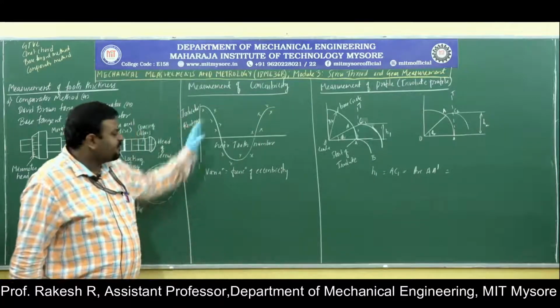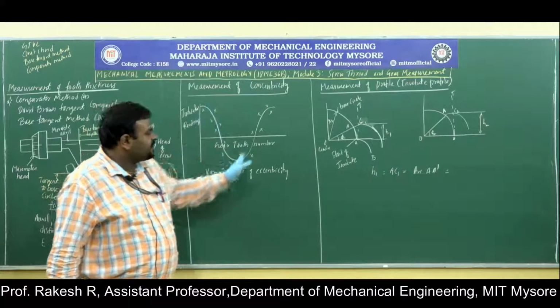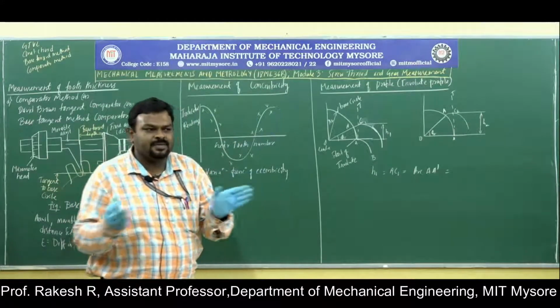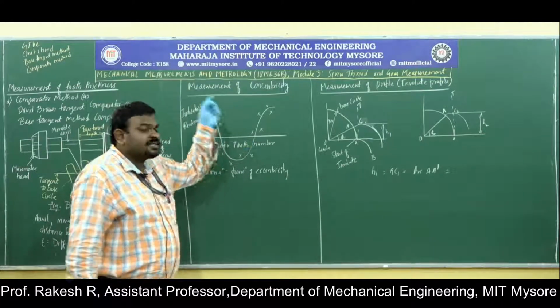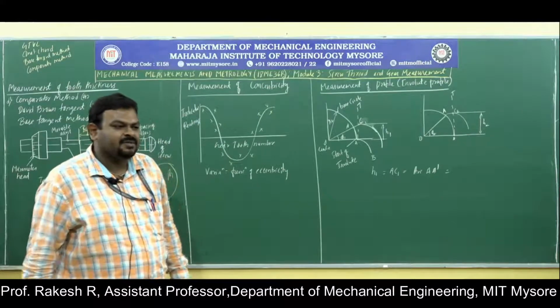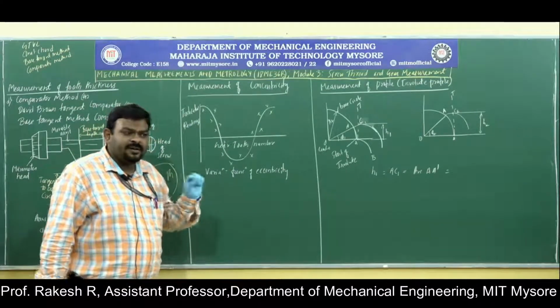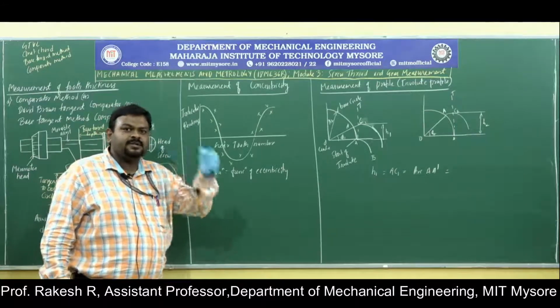Then after that, if you draw a smooth curve, that should be within this. If we say that it is within this, it is somewhat precise. All the teeth cannot have the same concentricity. There will be a deviation, so that deviation should be small. That should not exceed the limit.